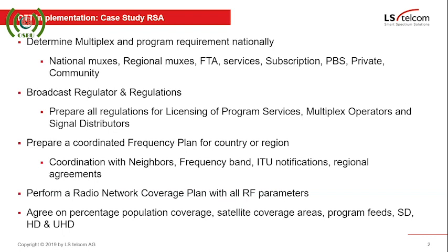With the flexibility of T2, you can have one single frequency network that is right across your country, and there shouldn't be any interference cases if you keep your guard interval large enough.